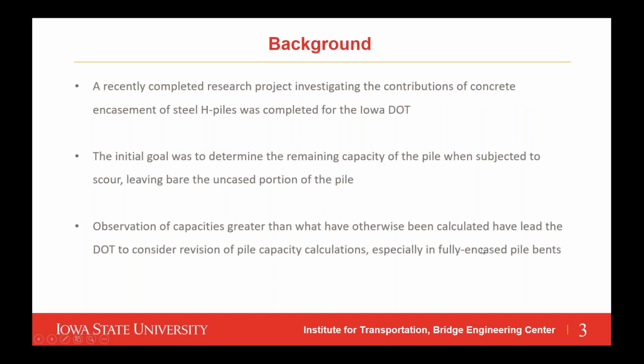Let me give you a little bit of background on why we're doing this project. We've recently completed another project for the Iowa DOT that was looking at the contributions of concrete encasement on their steel H piles. There is a standard design, which I will show you in the coming slides, where steel H piling are driven into the ground and then encased either individually or as a group with concrete.